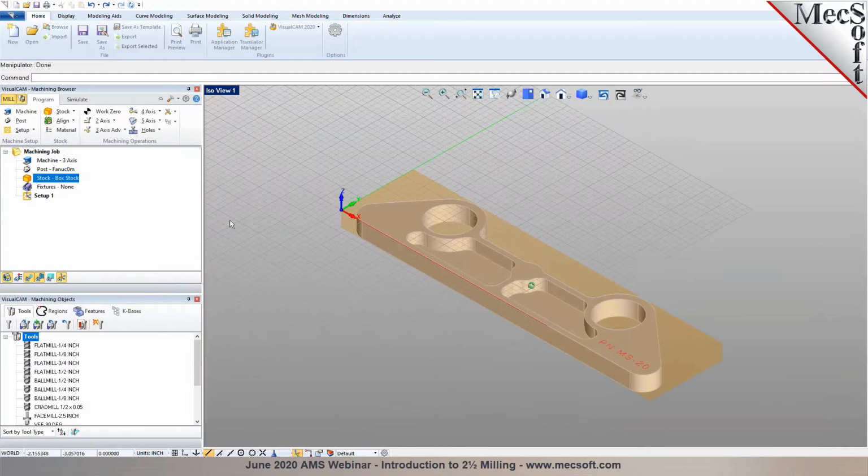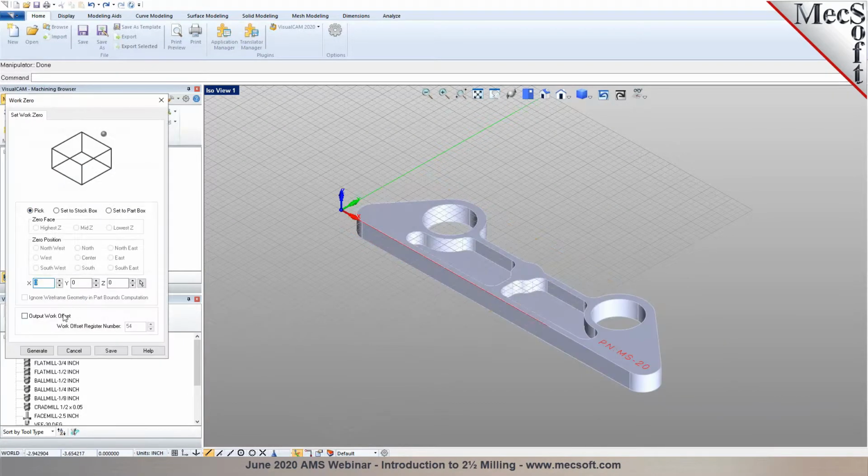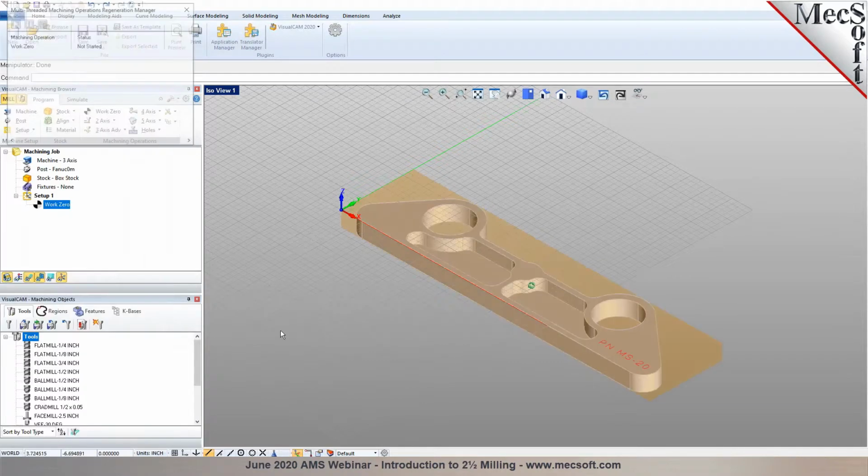So in the next step, we're going to start programming our toolpaths. If you need to create a works area to establish a work offset number, we'll just choose G54, leaving the origin at the same location.